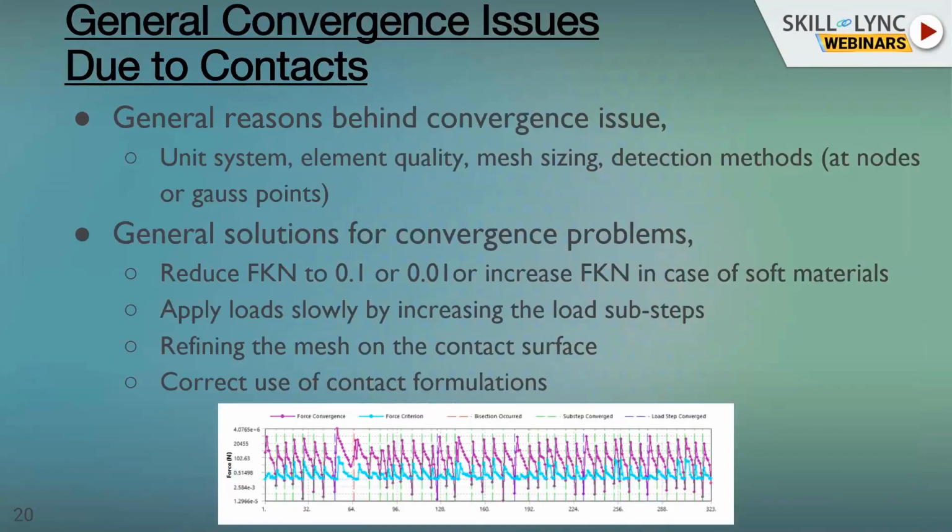So I think we have covered contact formulations, and how the nonlinearity is there in the system in the finite element method with respect to the contact. Then we have gone through the normal stiffness, how that normal stiffness is updated, and all those terms.